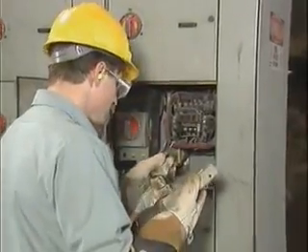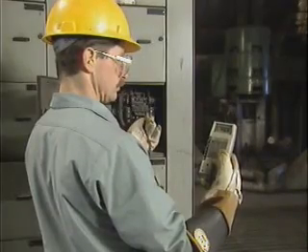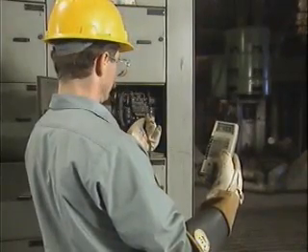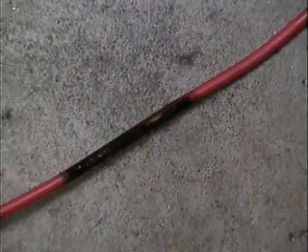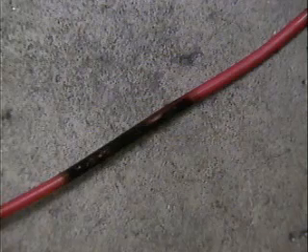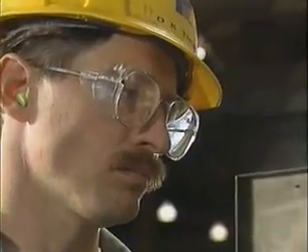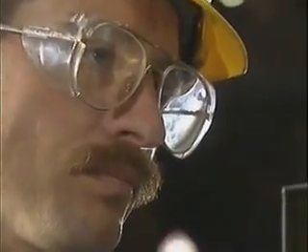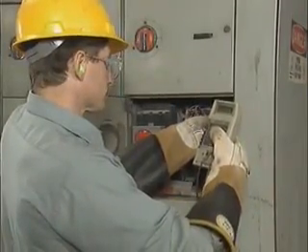In a case like this, an electrician may first attempt to locate the problem by testing the malfunctioning controller while it is energized. It's important to remember that you should test an energized controller only if the symptoms of the malfunction indicate that testing will not further complicate the controller's problem. For example, symptoms such as the smell of burnt insulation, sparks, smoke, or glowing wires are warning signals that you should not test the controller while it's energized. When you're working on an energized controller, you must follow all applicable safety rules, including the use of safety glasses and the properly rated leather-covered rubber safety gloves.